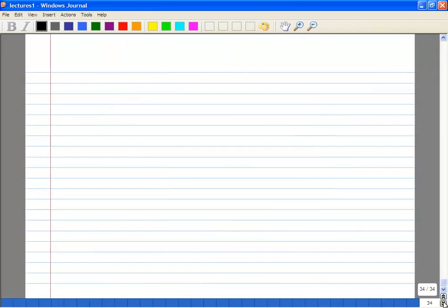Okay, so now we'll go back. We looked at parallel resonance circuits, and series is very similar. We just quickly looked at it and skipped it. I would definitely encourage you to try, whatever calculations we did for your parallel network, you should try it for the series network. You'll see it will be very similar, except instead of Q equals R over omega L, you'll get omega L over R and so on.